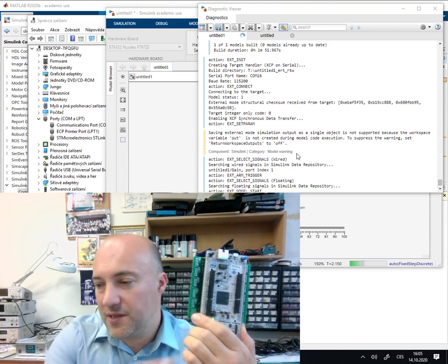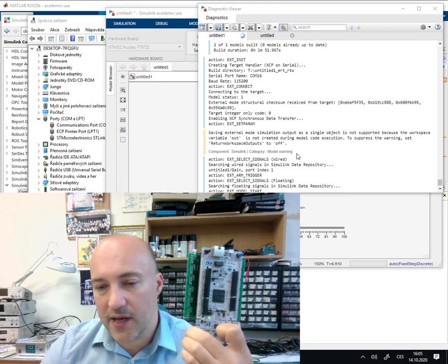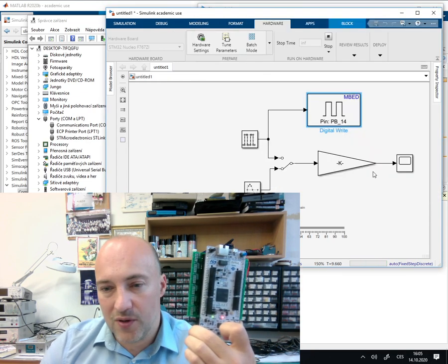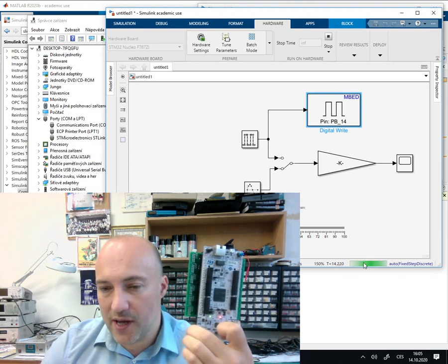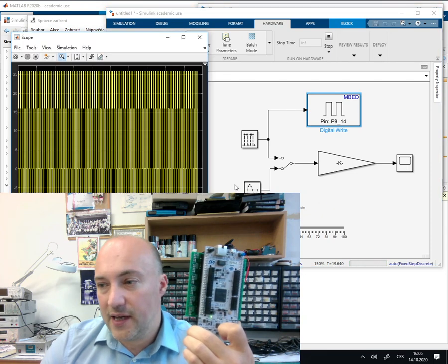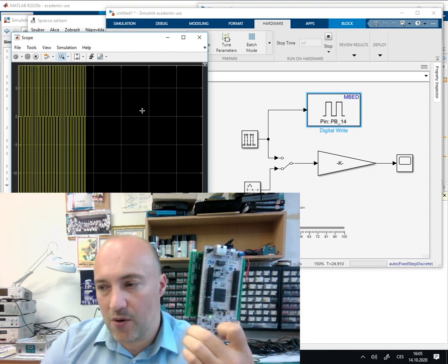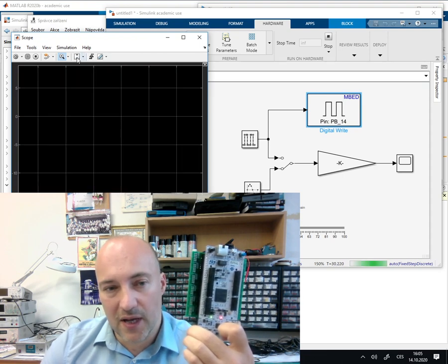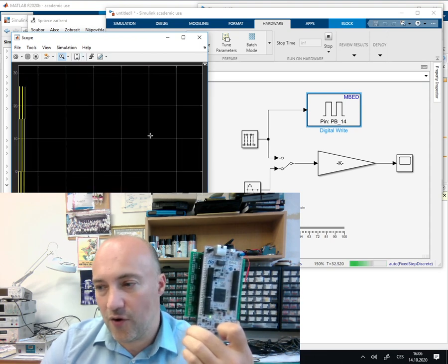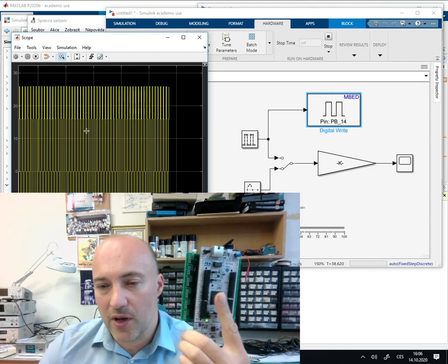and now you can see here this LED over there, the red one, is now blinking, and now this Simulink code runs. You can see it over there, how the time is running, and here on the scope, now this signal, that's actually what is coming from the real board. So it's not coming from Simulink running on the PC, but it is coming from the real board, from this one that is doing the calculations.